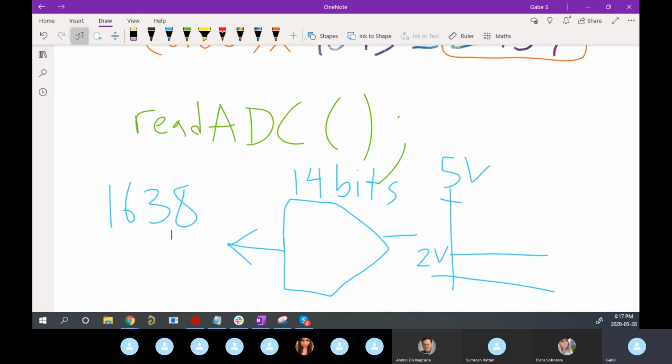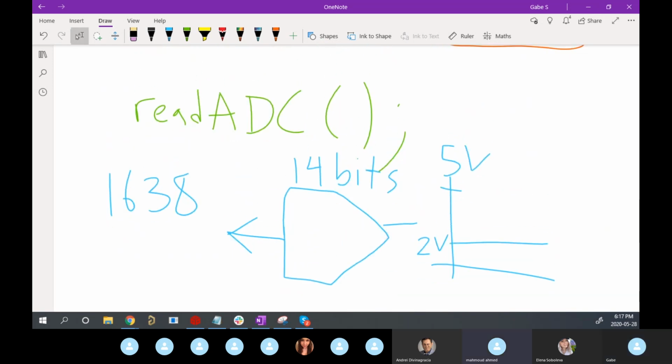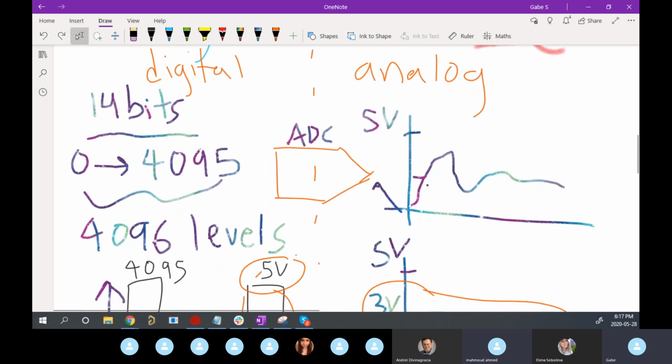And so you can imagine that if I think it's 6,553 if it's 14 bits. 6,553. Yeah, I may have skipped a power of 2. Because 4,096, is that 12? It could be 12. Yeah, that's 2 to the power 12. Thank you. Right, pretend I said 12 bits the whole time. Yeah, good catch. Does everyone understand what I did wrong there? So 12 bits means we have 2 to the 12 different levels. And that's equal to 4,096. And because we include 0 as one of those levels, the maximum value we can have is 4,095, right? So, good catch. Thank you very much.